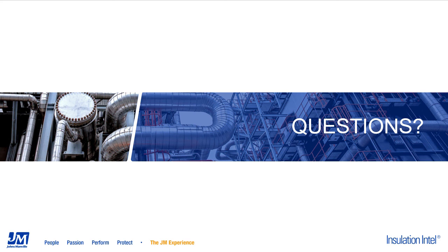All right, thank you, Jim. Yeah, Kim, I'd like to just jump in for a sec before you go to the next question. Back up to the question about Insulin and stainless steel. I would like to add to my previous answer that we do have all of the test results related to corrosion with austenitic stainless steel as they relate to the ASTM standards of C795, C871, and C692, demonstrating that Insulin does pass all of the requirements for that type of an application. So we do have that additional data as well.